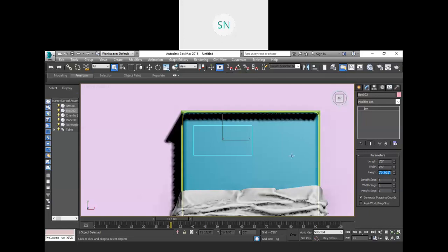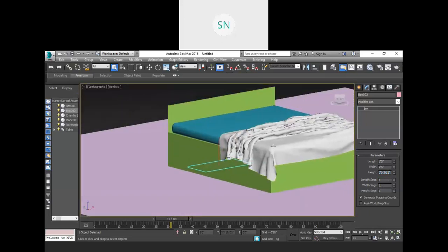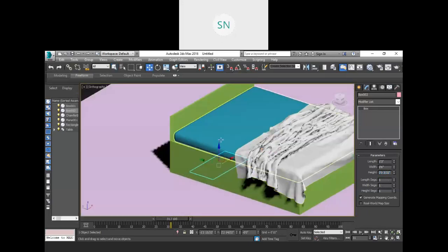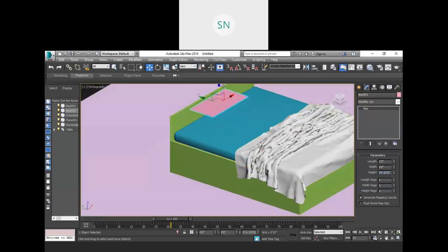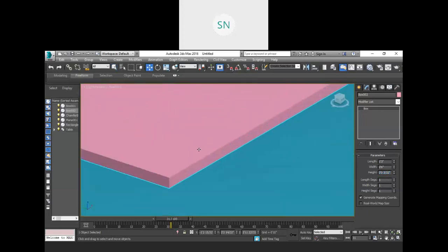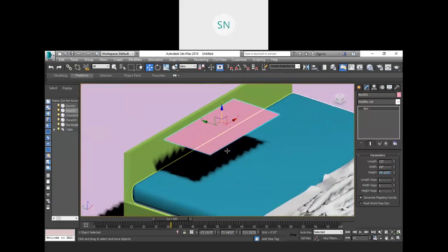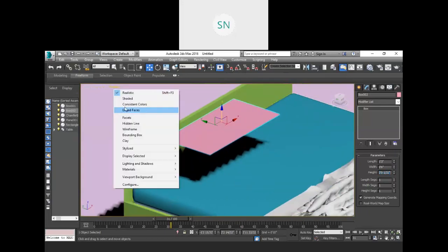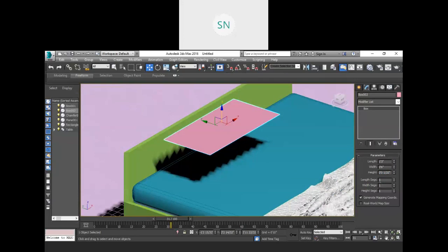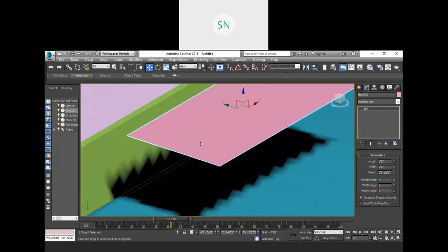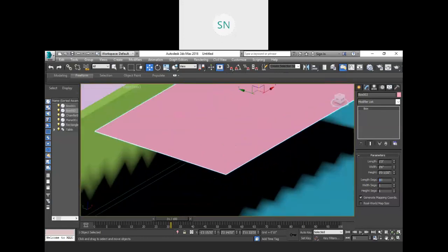Number of segments are also necessary because in the clothing, right, so first let me take this thing out so we can view it. Let me reduce this size again, 0.05 inches. Okay. Now turn on the edges and provide the length segment. Length is 1 feet 3 inches. So we will add around 100 first.